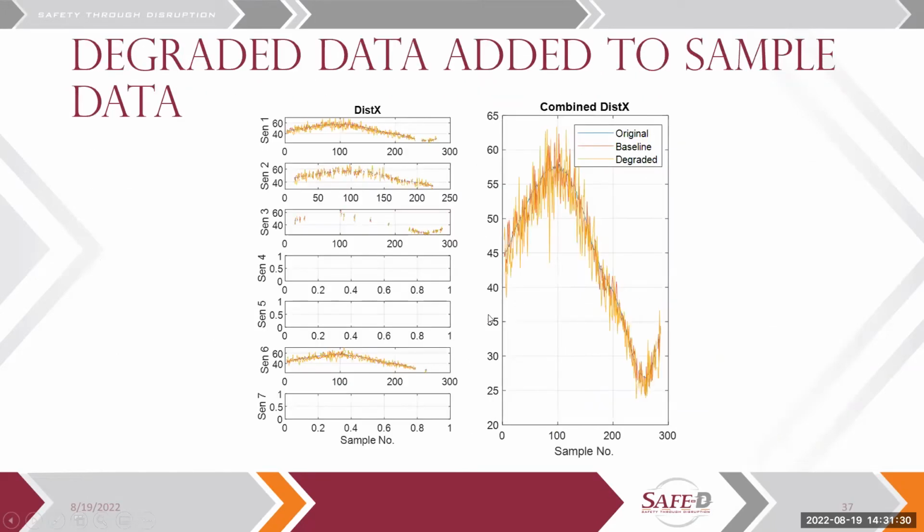And then lastly, here we have some of the sensor data. These are the X distance, longitudinal distance for the different sensors we had on the vehicle. And of course, it's picking up the vehicle in some of them and not in others. And these are looking at oblique angles, so they see even less. But all that can be combined, and you get the full track of the object within view, with the signal noise added to the perfect data that we get out of the simulation.